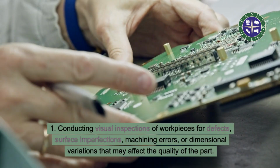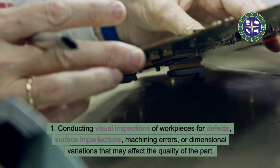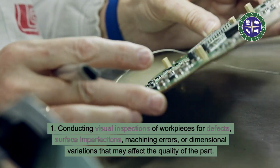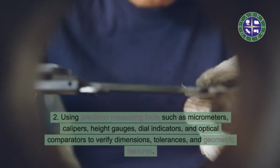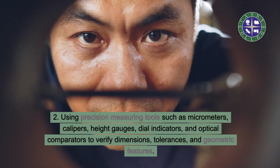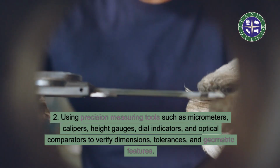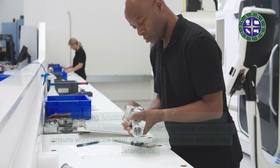1. Conducting visual inspections of workpieces for defects, surface imperfections, machining errors, or dimensional variations that may affect the quality of the part. 2. Using precision measuring tools such as micrometers, calipers, height gauges, dial indicators, and optical comparators to verify dimensions, tolerances, and geometric features. 3.